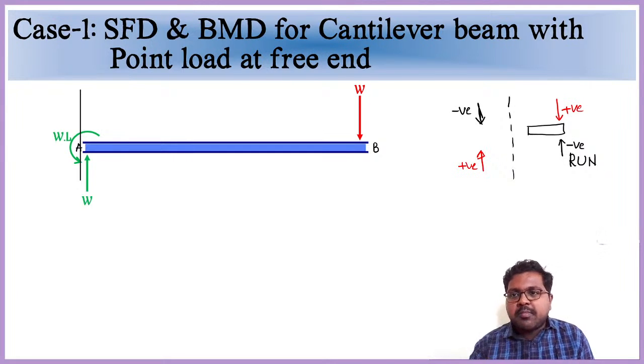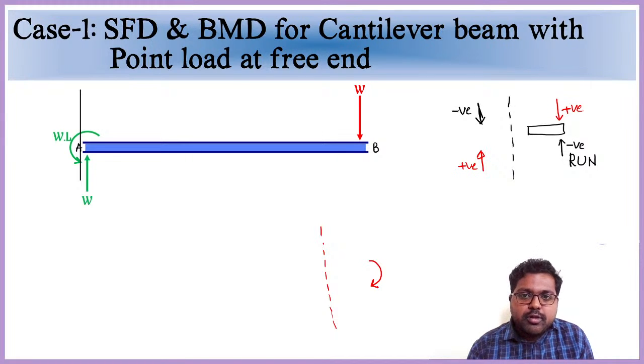We need to remember this terminology while drawing the shear force and bending moment diagrams. At the same time, we have to follow the bending moment sign convention also. On bending moment: if on the right side it is creating a clockwise moment, see, this load W, just now we discussed, is creating a clockwise moment.